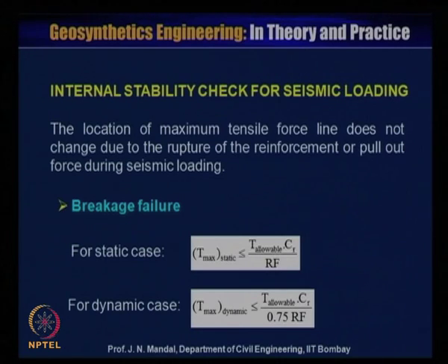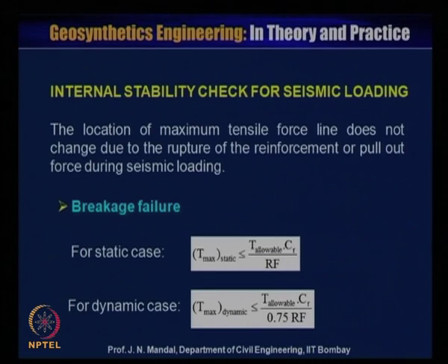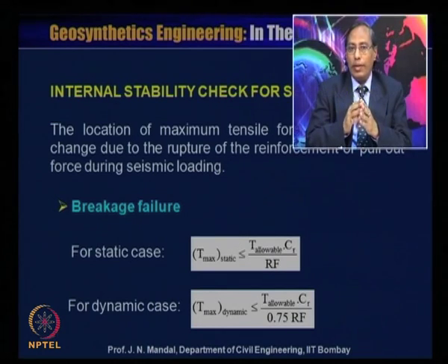Now, for internal stability check for seismic loading, the location of the maximum tensile force line does not change due to the rupture of the reinforcement or pull out force during the seismic loading. We are assuming that the maximum tensile force line is the same as in the case of the static case.